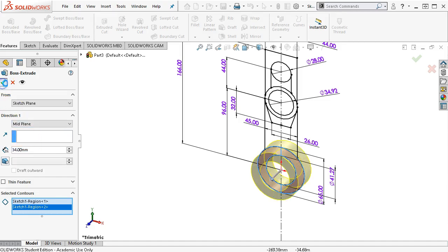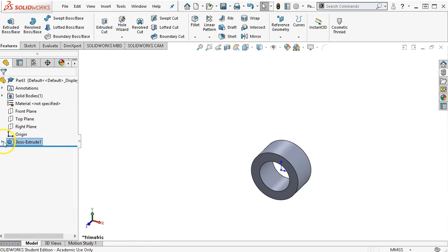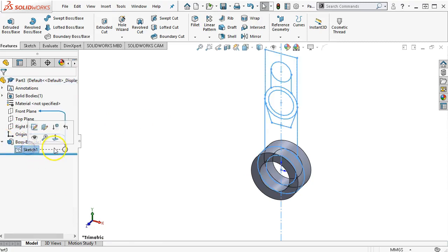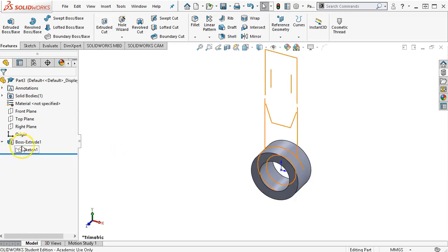I'm going to go ahead and hit OK. The next portion up is still rectangular, and I'm okay with the through hole down here, but getting into this geometry and the intersections, I'm not quite so sure about yet, mainly with the bosses coming out the side. So I'm going to show the sketch so that I can get back into it easy enough.